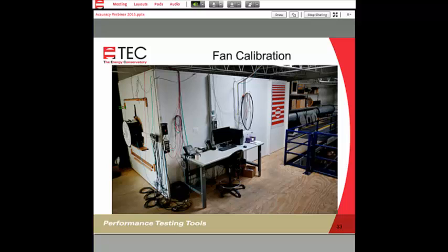And you see a number of pressure gauges here, and our attendant that works on the fan calibration basically changes the orifice plates whenever they're needed when we're changing ranges. But otherwise, it's all automated in ramping up the flow of the fan and comparing all those values to our standard values.